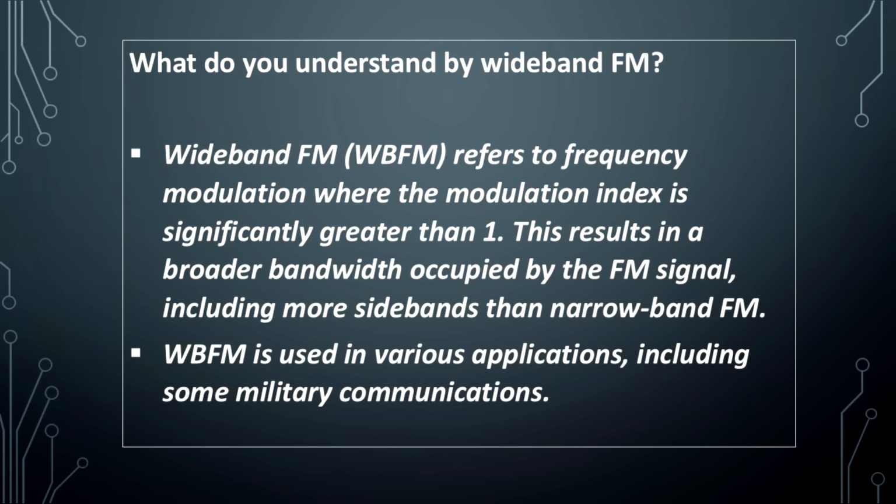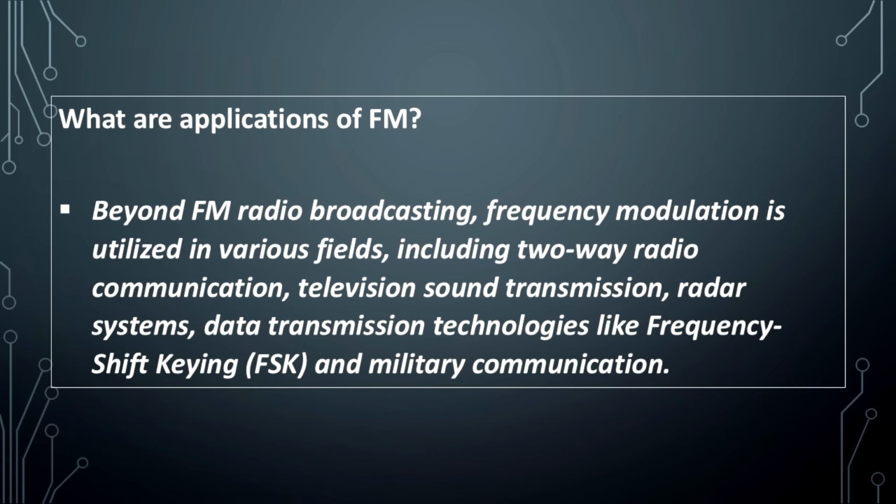What do you understand by wideband FM? Wideband FM refers to frequency modulation where the modulation index is significantly greater than 1. This results in a broader bandwidth occupied by the FM signal, including more sidebands than narrowband FM. Wideband FM is used in various applications, including some military communications.